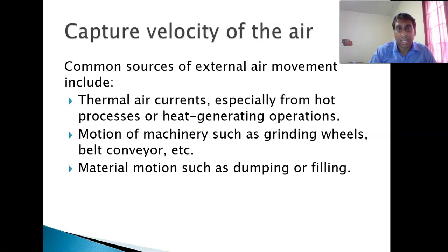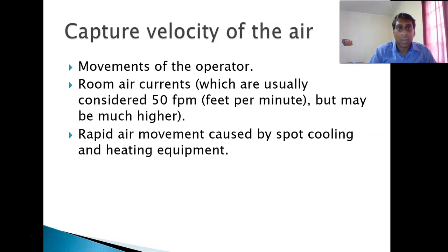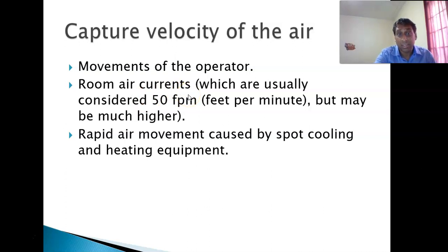So you may have thermal air current. The very fact that an employee may walk creates a disruption to the airflow, right? So you have your movement of the operator, room air current, especially if you have fans in the room in addition to the LEV system. All of those are competing systems for the suction in the LEV system anyway.